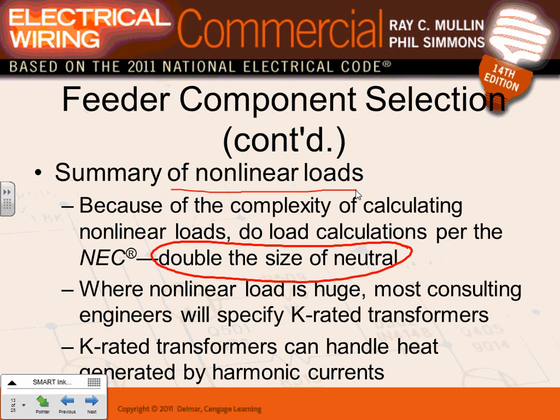So what do we do, guys, for a lighting panel or receptacle panel up to 300 amp? Between 225 to 300 amp, what do you do? Full neutral. Do you know why we do full neutral? Because if we do full neutral, the worst scenario is the neutral will have harmonics and it will have as much current as a phase. So you almost cover the worst scenario. That's why we call it full neutral from here.